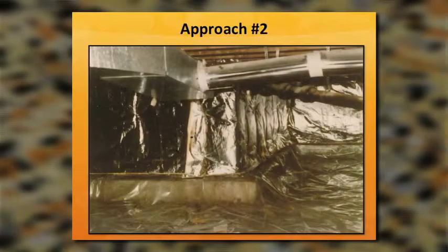So that's why building science has moved to approach number 2, which is a very good moisture barrier on the dirt of the crawl space, and then insulate the foundation walls going all the way across, and then we seal up all of the rim joists. And if there were crawl space vents there before, we make sure that those get sealed up nice and tight. And we actually bring the crawl space or the basement inside the thermal envelope.